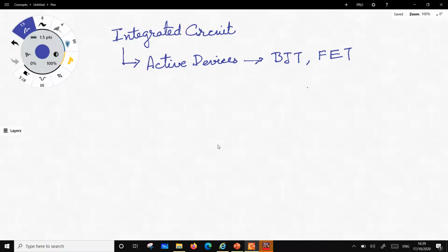So these days we don't use metal, so basically this name is not exactly correct. We take the gate oxide, and top layer of a gate oxide we implant with ions, and then it becomes a conductive poly. So the gate, which basically controls the flow of carriers between source and drain using a vertical field. Okay, so that basically is no longer using a metal, it is using a conductive polysilicon. So field effect transistor, so simplest is a MOSFET.